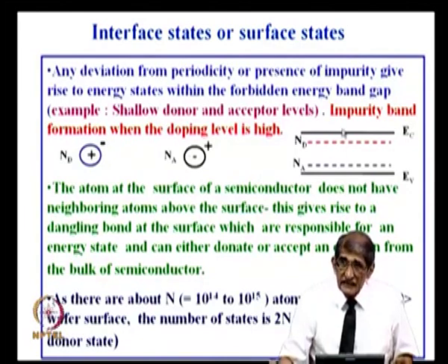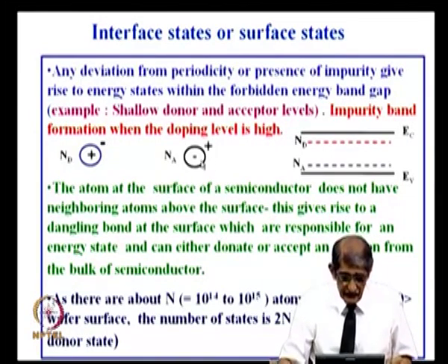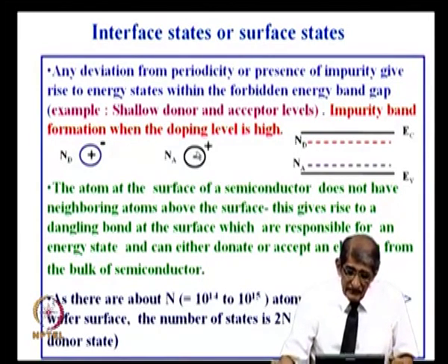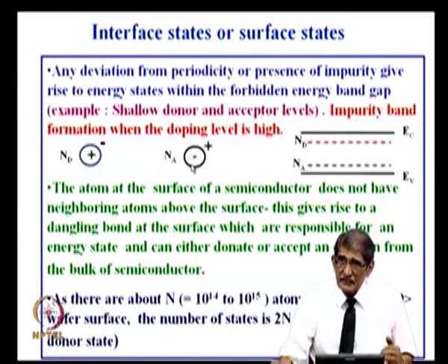Okay, that is why I put it near the conduction band. Why I am going through this is because we want to see what happens in interface state density. If you take a donor, the core is plus; if you remove the electrons from there, it is positively charged. For an acceptor, the core is negative; there is a site with plus charge, which you can look at as the vacancy, so you can assume that there is a plus charge.